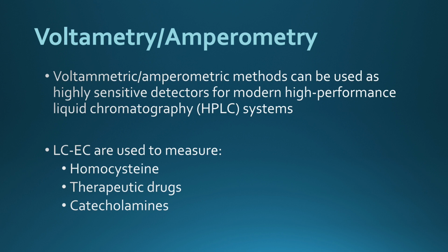Now, ion selective electrodes, and potentiometry and electrochemistry in general. What do you think the advantages of using these methods are? Not very expensive. Exactly, it's not very expensive. In fact, a single electrode is not cheap, but the good thing is that once you load it on the analyzer it can stay for about 3 months or 2 months depending on the load. So when we look at the overall cost, it will be cheaper than other options. The cost, yes. Ease of what? Ease of use. How is it easy? Because it's automated. It's not manual. I can adapt it in automated analyzers.